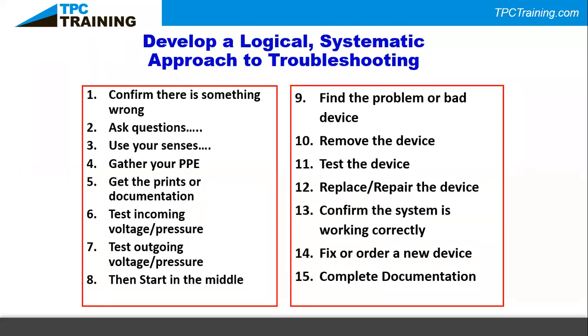Complete the documentation of the process that you followed for the troubleshooting process, and that means filling out and completing the work order for the process, saying exactly what you did to solve the problem, and filing that into some sort of central documentation system, whether it be a maintenance organization system or in some sort of central file sharing system.